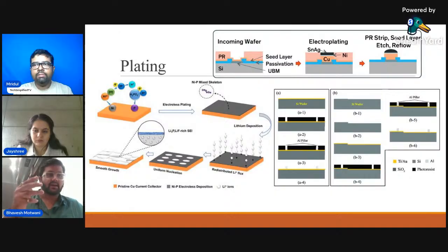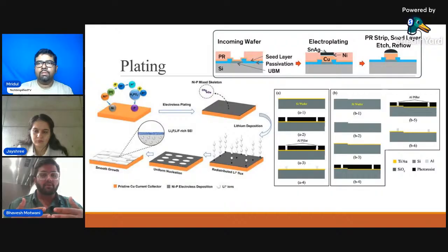And these are connected at a memory level. We see 3D IC packaging, 2.5D IC packaging, even right now 4D packaging is being done. So generally we make SoCs and then join them one upon one to make a whole building, like a stacking. Plating can be very easy for making a small package where everything is integrated in one package, and plating is very helpful to make a proper conductive layer. Even as a conductive layer, it should be corrosion-resistant, or needs to be protected from corrosion. So plating is generally done for a better connection.